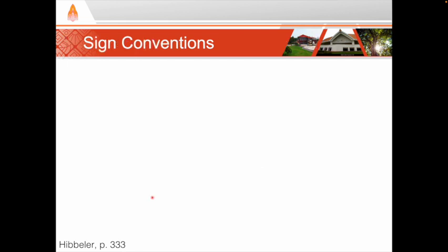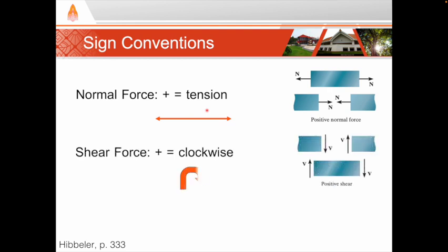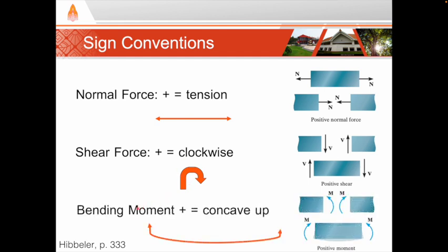Before we do that though, let's establish sign conventions. In other words, what do we call positive or negative forces? For normal forces, positive is defined as a force that creates tension. For shear forces, positive is defined as a force that acts to rotate the member in a clockwise direction. For bending moment forces, positive is defined as one that bends the member in a concave up manner.